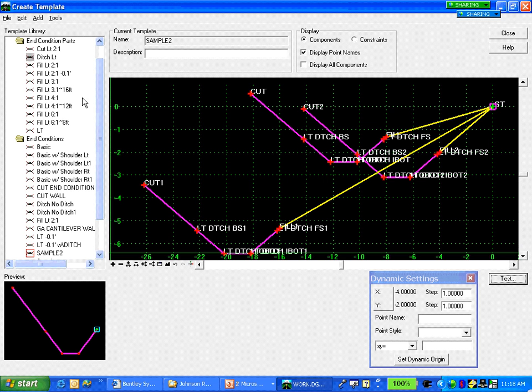and I can make this a relatively short segment, but in the interest of time, and since I have these available to me, I'm just going to come over here and take my 6-to-1 segment, and drop it in right there, all right? And so this is going to give us multiple targets here. We can look up or look down. I'm going to come over here and take my 3-to-1 segment, and we'll drop it onto this point here, which was the end of our initial 3-to-1 slope. And finally, I'll select my 2-to-1 slope, and I'll drop it up here.